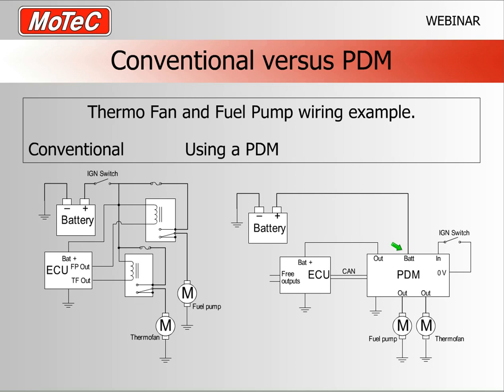So this allows us, even in a simple application, to reduce our wiring complexity, but it doesn't take much imagination to see that if you had a very large, complex wiring loom, this PDM is going to give you a massive reduction in wiring.